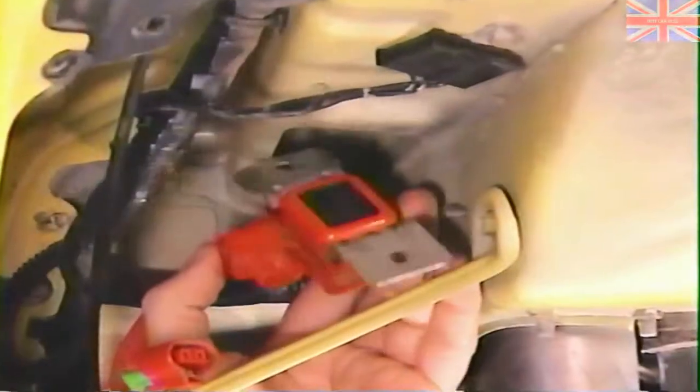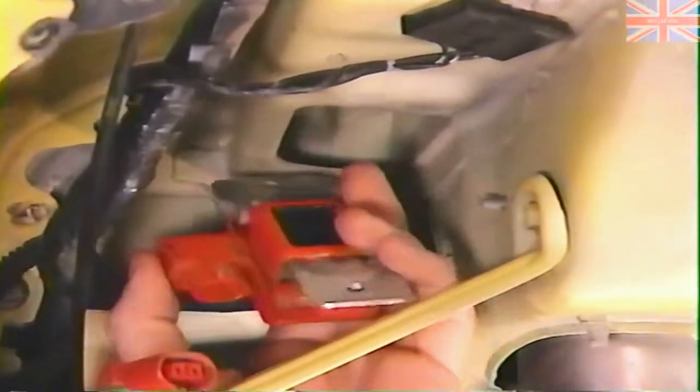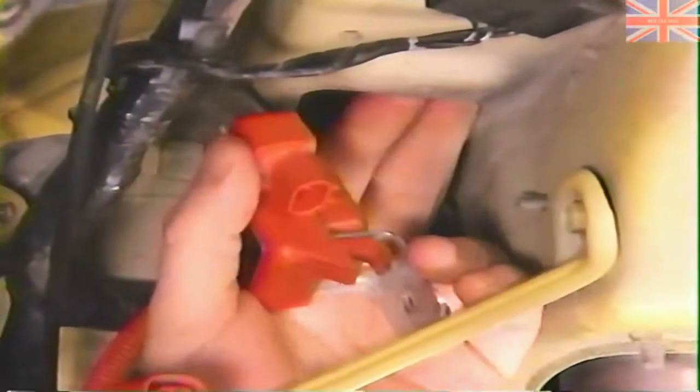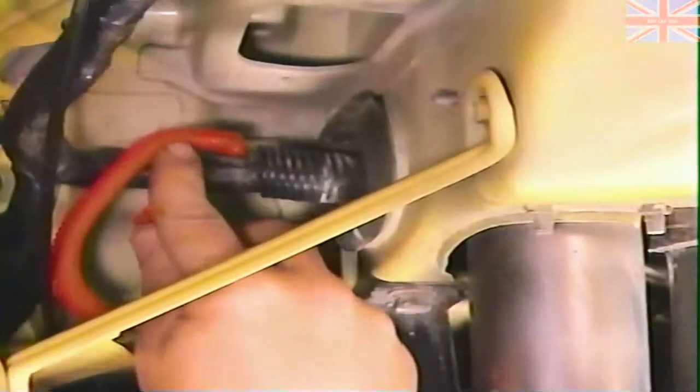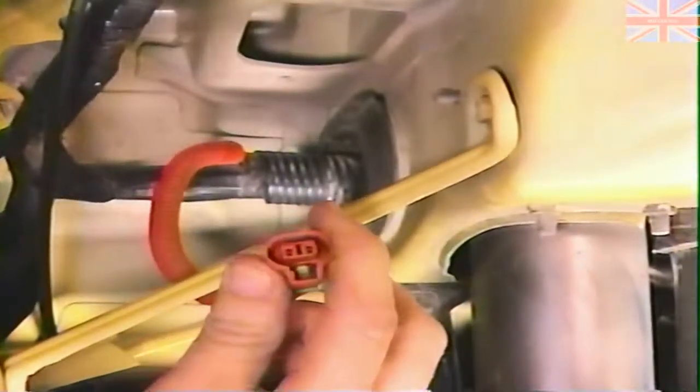If the vehicle was in a low-speed or non-frontal collision in which the airbags did not deploy, check all components for damage and replace them if necessary. Check front impact sensors and their mounting surface for damage or corrosion. And check for wiring harness and connector damage.